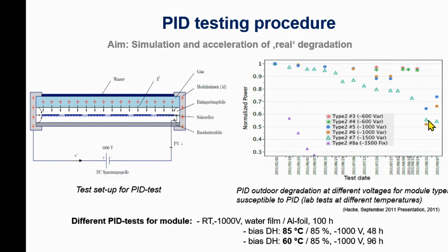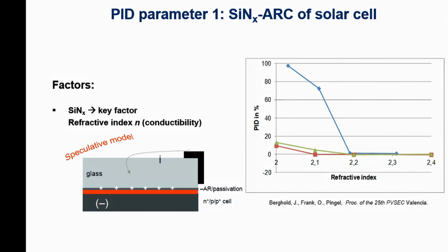You see this degradation at different levels. In order to standardize the test procedure, because each test lab formerly had its own procedure, it's called IEC 62804-1. This carries out some tests to define temperature and so on. Parameters which are responsible for those tests.